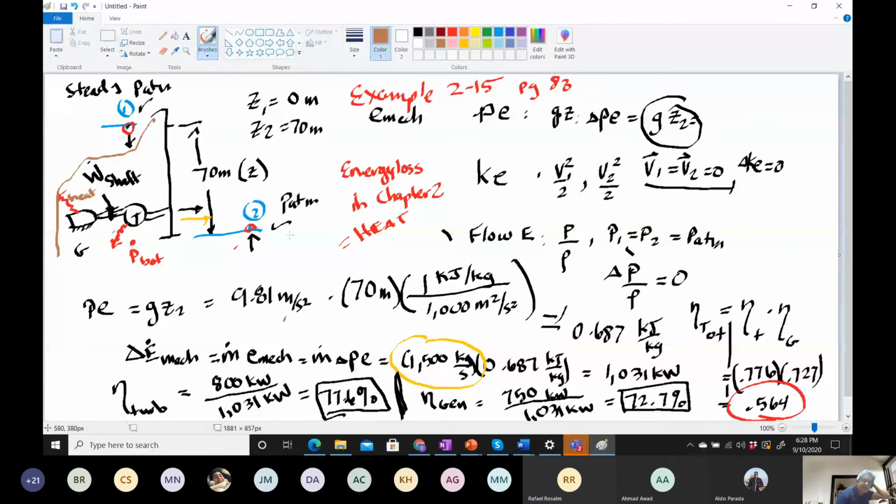If you actually did the math, the electric generator can only really convert what's coming from the turbine, and that's 800 kilowatts. Of that, it's generating 750, so it's only losing 50 kilowatts of the total 800 going in. And then if you do the math, it's somewhere probably in the 90s. Yeah, it's 93-point-something percent. So it's very typical for a generator. Thanks, Professor. Okay, you're welcome.